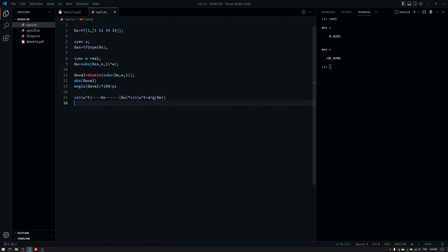But in the industry, when we are designing PID controllers, we are most of the time concerned with the low frequency range for certain aspects and high frequency for noise and stuff like that, because that's the nature of things. If you're in a car, if you're accelerating, then the frequency that you're interested in is the low frequency range for tracking.